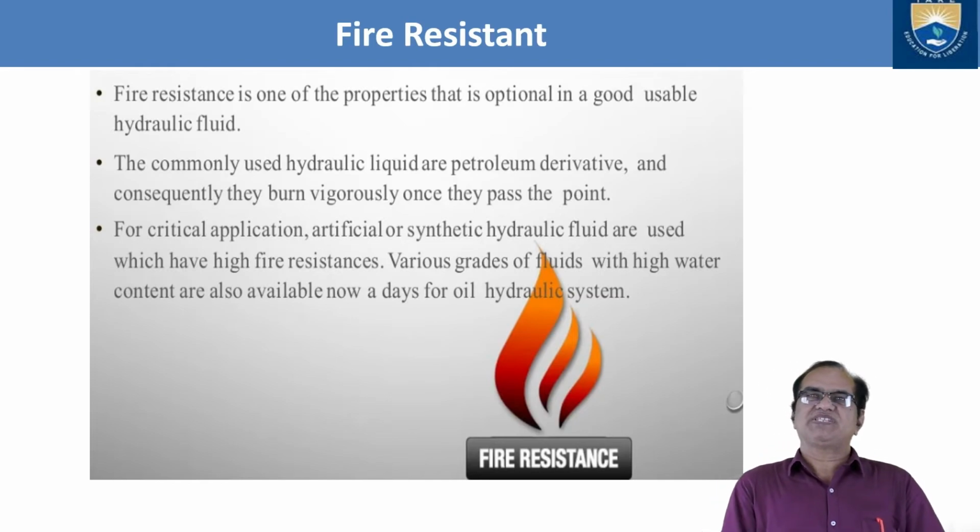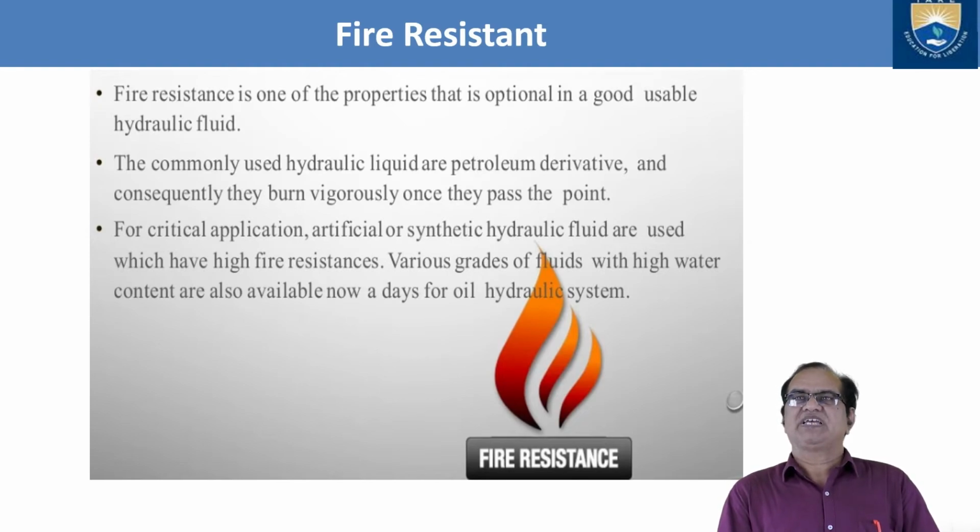Next is the fire resistance. Fire resistance is one of the properties that is optional in a good usable hydraulic fluid. It is very important that the hydraulic fluid should be fire resistant. The commonly used hydraulic liquids are petroleum derivatives, and consequently they burn vigorously.